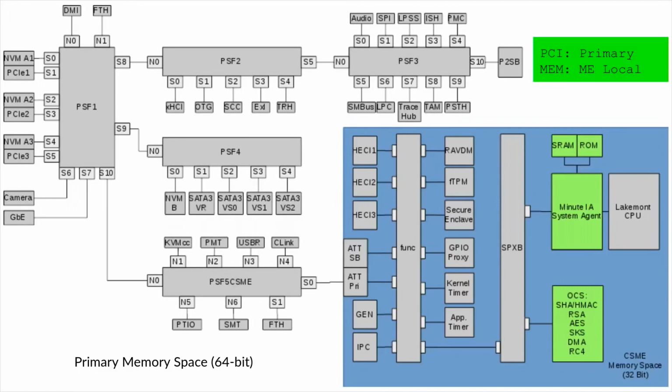So it has bus device function numbers, PCI configuration space registers. And they have two different routes for the configuration space. So even though the configuration space address includes a bus number, they have two completely different things, each of which has its own bus 0. That's weird also because they don't make sense when you look at how the hardware is laid out.